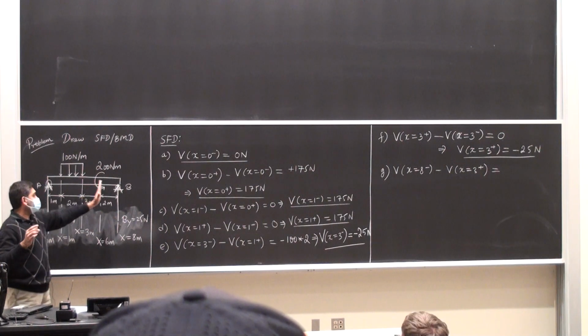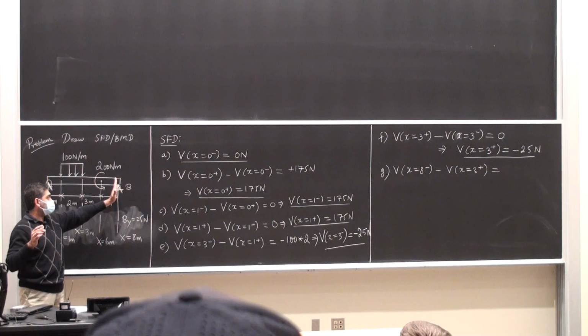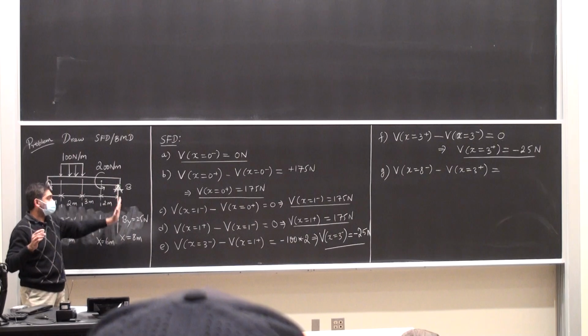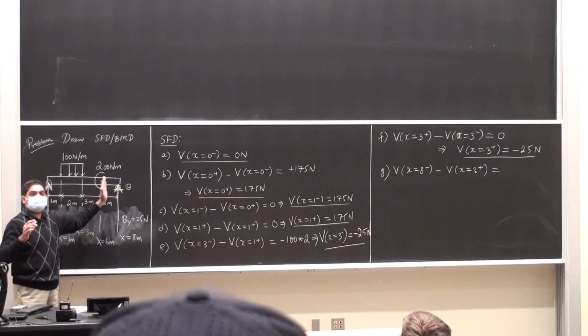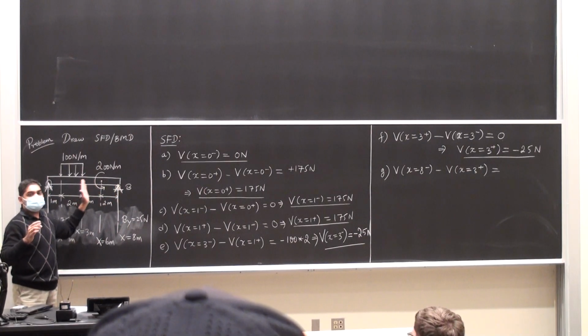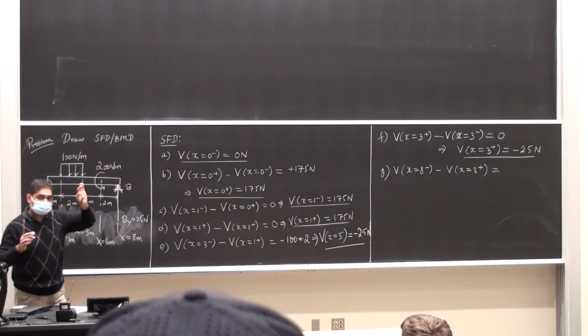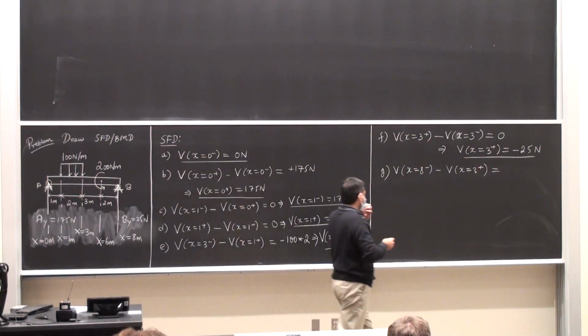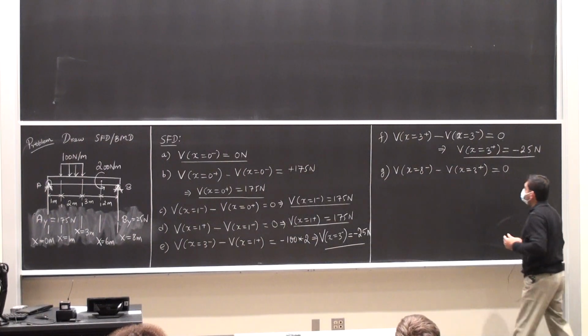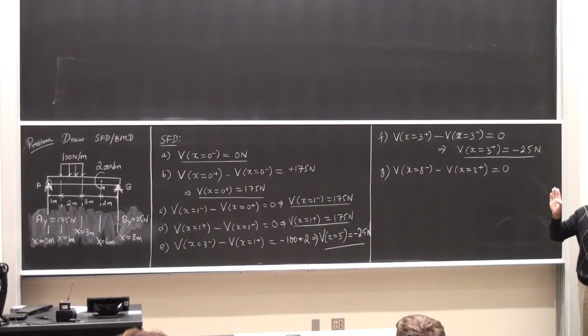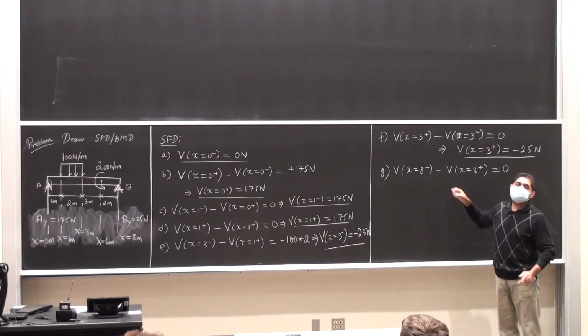Between 3 plus and 8 minus, where I am stopping short of this concentrated force, is there any force acting? Is there any distributed loading acting? Which means that the change in the shear has to be 0. Okay? So think carefully. Don't be fooled by these concentrated forces. That is why we are doing it in this really painstaking manner.